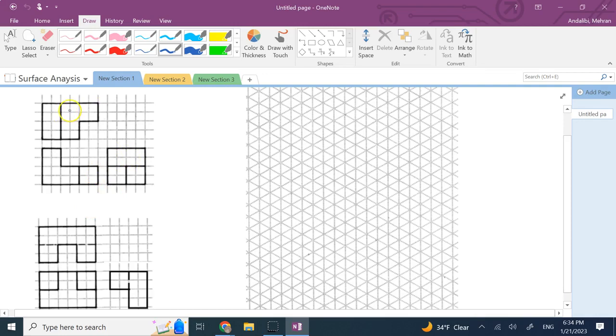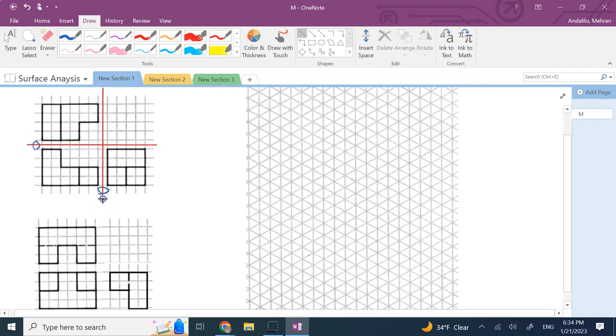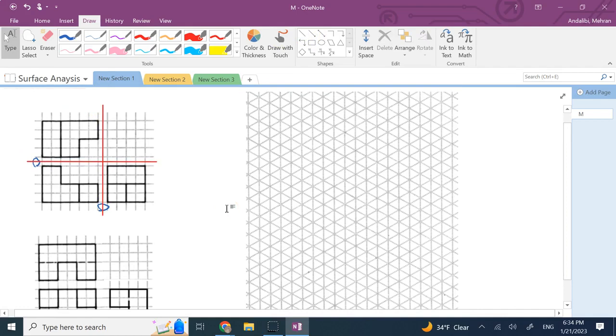dimensions between top and right view, is if you look here, the gap that you have between front and top is 1 unit. The gap between front and right is also 1 unit. So if I want to draw a line between folding lines, I draw it exactly in the middle, right? So here I go and I draw it exactly half of that 1 unit. Let's see if I can roughly get something like that, right? So I do something like this, and then here I do the other one. So I put my folding lines somewhere like that.